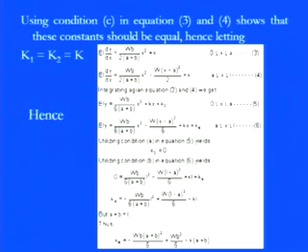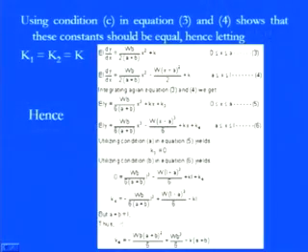So by keeping those things, what we have is the k4 value, and this value is nothing but equal to minus WB divided by 6 times (A plus B) L square plus W times (L minus A) whole square divided by 6 minus kL. So now you see you have all the values of the constants. We know that the total length of the beam is L, which is divided into two portions A and B, so A plus B equals L. So L minus A will give you B.